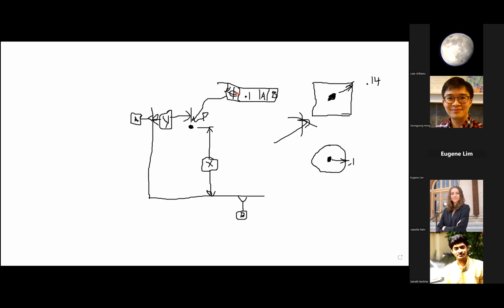So that is essentially the main advantage of using GD&T. It makes it a lot more specific as to exactly what tolerance and what your limits are for your drawing. And so this makes it a lot easier for you to fit a hole where you need it to be. And it gives a machinist datums to use to accurately put that feature.